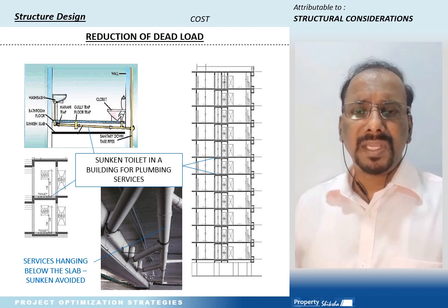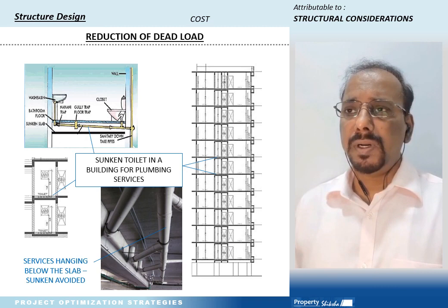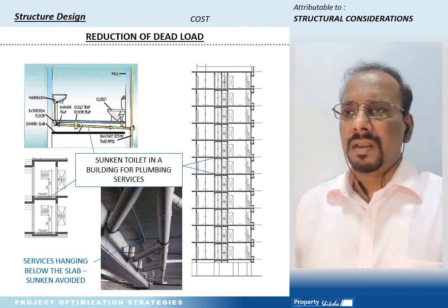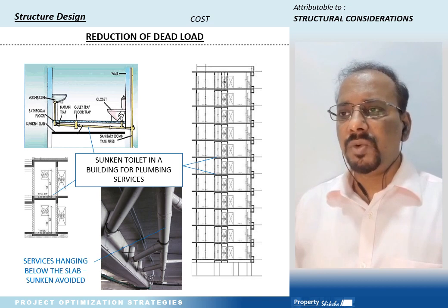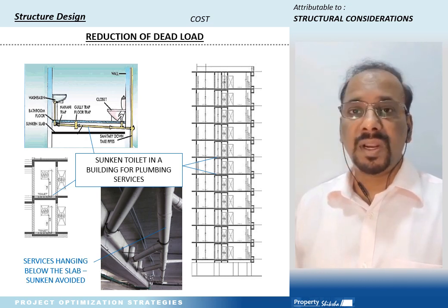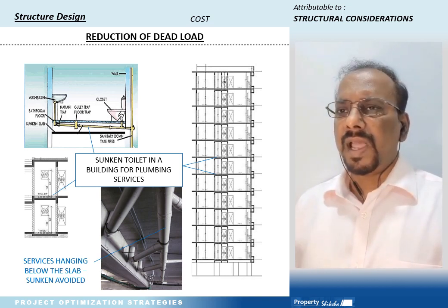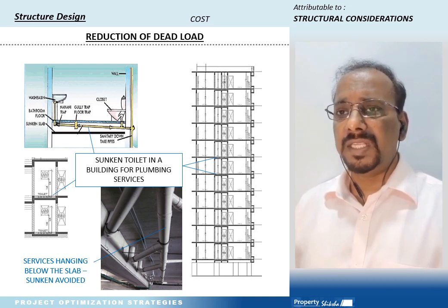Under project optimization strategies, my next point affecting the cost of the project and attributable to structural conditions is related to structure design. Under structure design, it is advisable to reduce the overall dead load of the structure, where one of the strategies is to reduce the filling, or reduce the depth or extent of sunken area. The diagram over here explains the particular point, where the upper diagram shows the sunken area where the filling is proposed